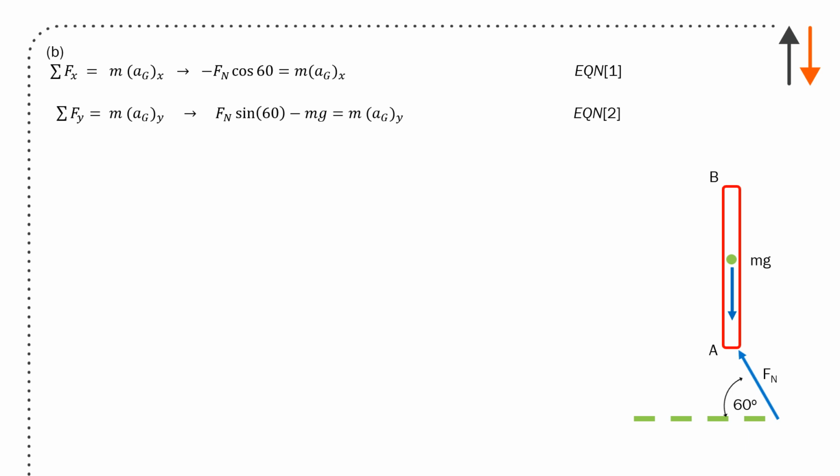And that's m a_x, and that's acting in that direction. And for Fn y, it's acting upwards and it's positive. Weight is acting downwards, and you have m a_y. You expect this also to only have a component from the normal force x, and that will cause a rotation that's clockwise, Fn cos 60 L over 2.